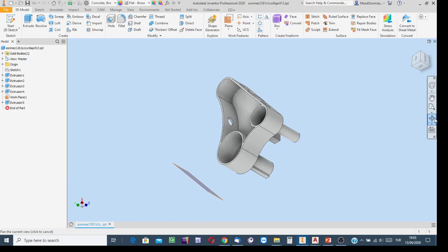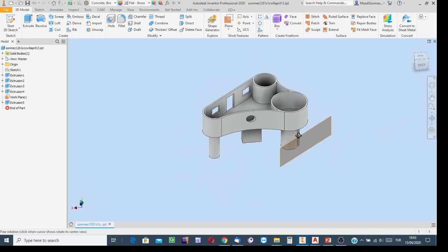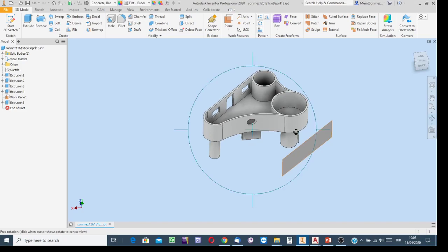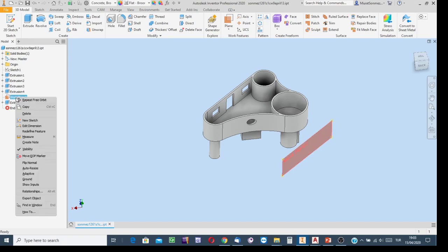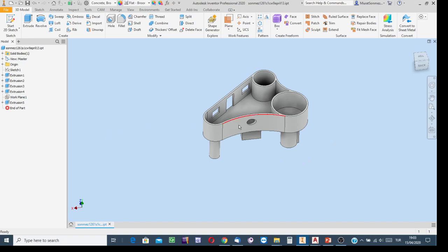Yes, you see, we managed to create this empty space. And then if you use a work plane, there is no need to keep it visible. After finishing the necessary work, bring the cursor to the browser. If you invoke the work plane using this facility, there will be a corresponding work plane icon. Right click the mouse to make it invisible. Take the visibility of it off the screen. Deselect this visibility option.